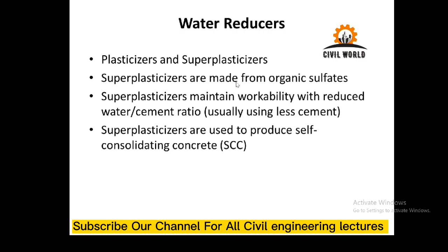But self-compacting concrete has good workability and good flow properties, so it does not require any type of vibration for its compaction, and it flows under its own weight to compact in congested areas. Superplasticizers are mostly used for production of self-compacting concrete by increasing its workability to an extent where concrete has self-flowing property.